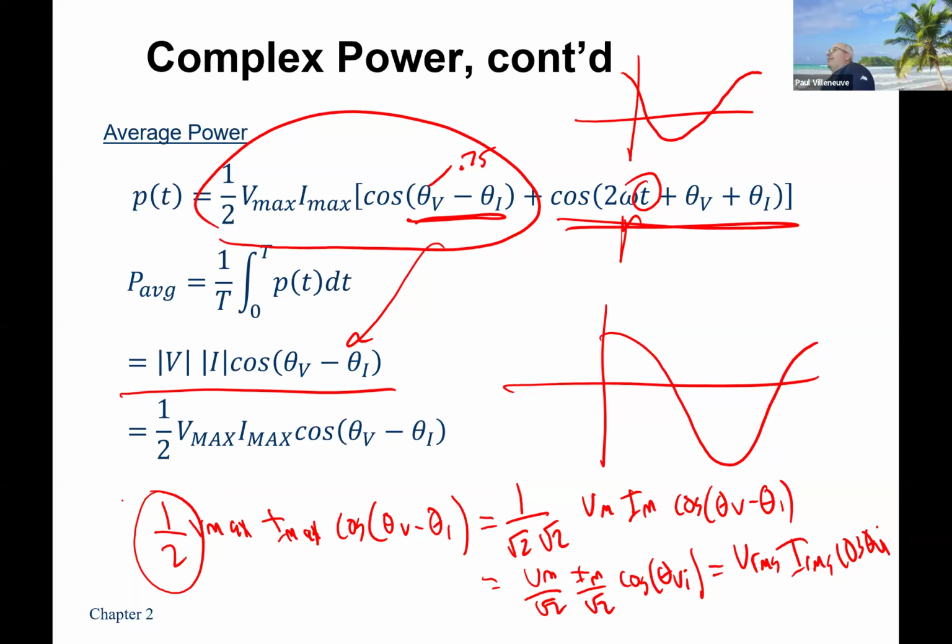So if I plug in my laptop here, which I did, I'm not seeing 120 volts. I'm seeing a sine wave that varies between plus and minus 167, right? But because I can't make my calculation work by using that plus or minus 167, I just say that it plugs in at 120 or 240 or 277 or 480 or 345 kV, which again is the highest line-to-line voltage in New England, not counting DC.